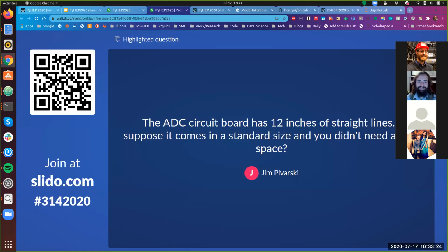Okay, so to get back to why the length, you just want to irradiate the chip. All of the other FPGA, USB controller things, those are not radiation hard. So we put everything on the right-hand side of the, or whatever side of the board it is. The far one side of the board is covered by lead bricks, and we just expose the ADC itself. So that's the only thing that gets irradiated.